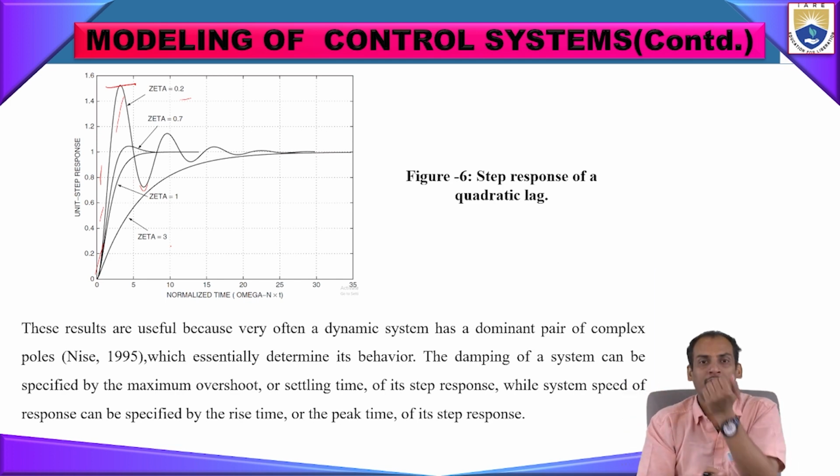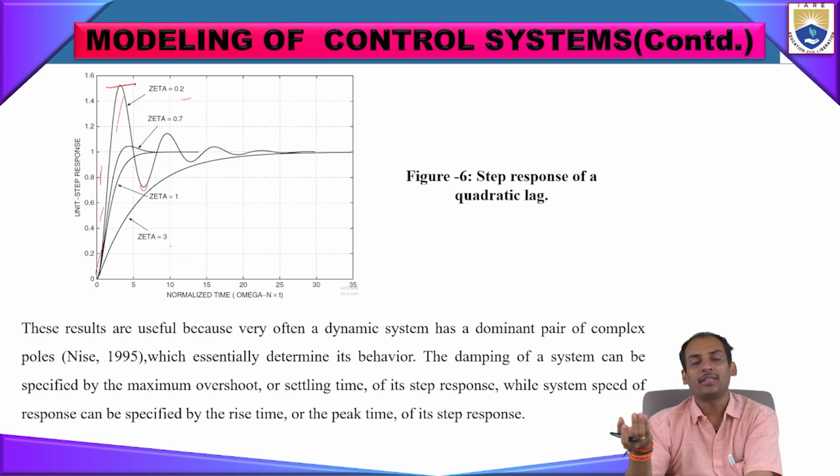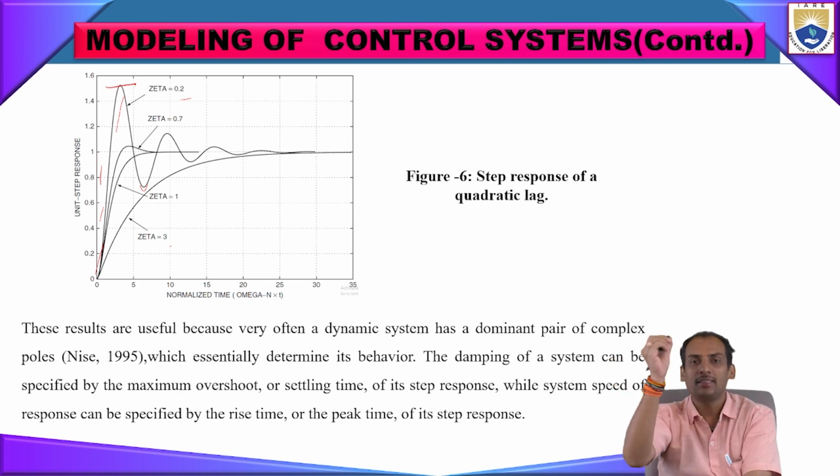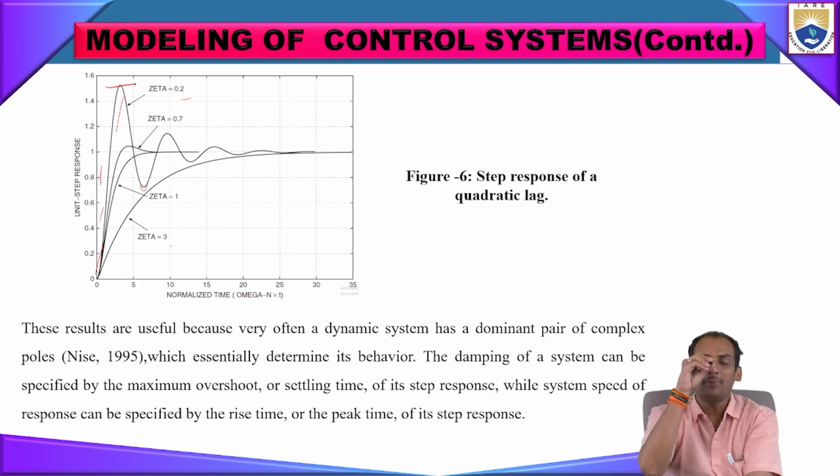If you see the displacement out of the autopilot or SAS CSS system, we are giving one input to that control system. Due to that input, it has been converted into a transfer function, and that transfer function gives the roots in the Laplace variable. Depending upon those Laplace transform values, we have got these frequency response and time response plots. For this input, the frequency response and time response will behave like that. Based on that we can have an approximation that this system will behave like that.